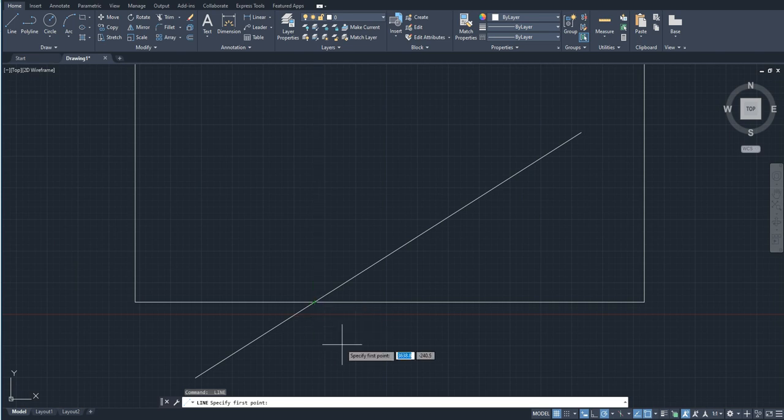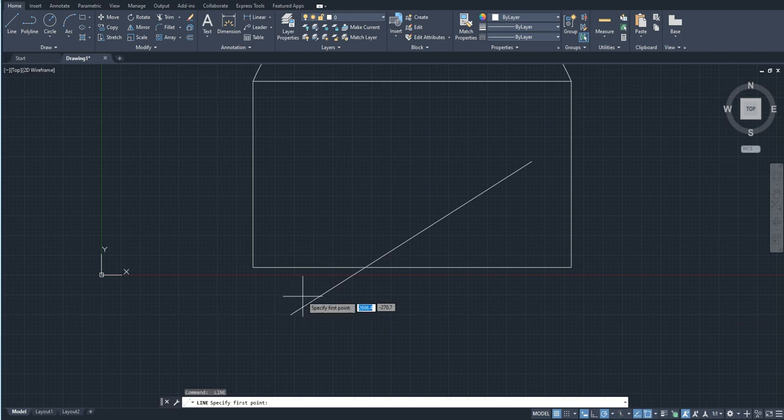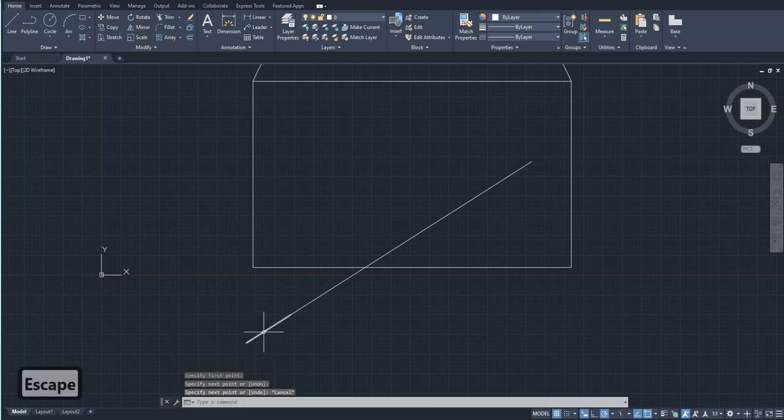The next is extension. Suppose I want to make an extension of this line. It's a bit tricky. I just click on the endpoint and you see I can't make an extension over here. But if I just hover over this line and then extend my line over here, I can make an extension of this line. It's written extension 676/212 degrees. So that's what it is. That's the extension, people. The next is perpendicular.